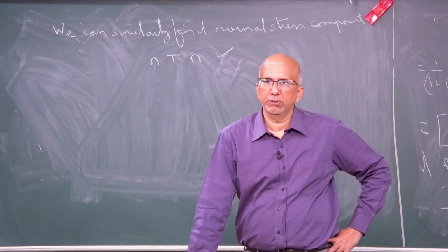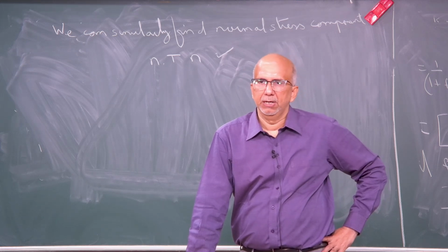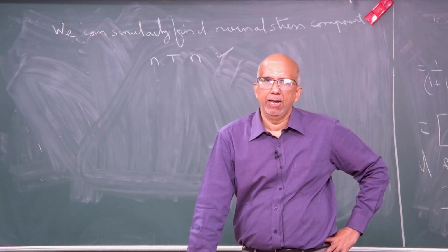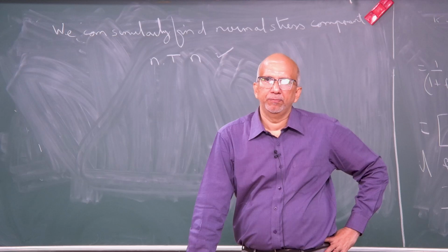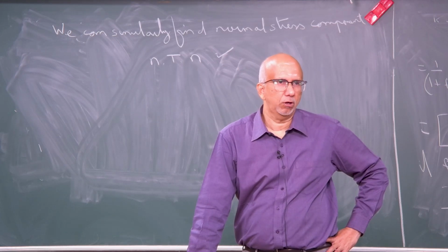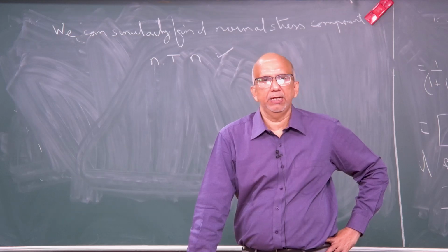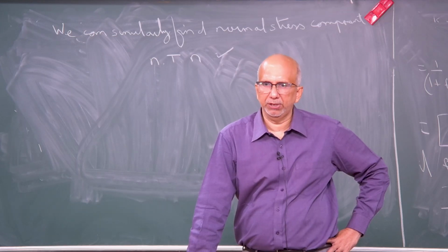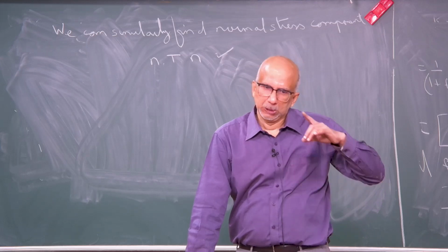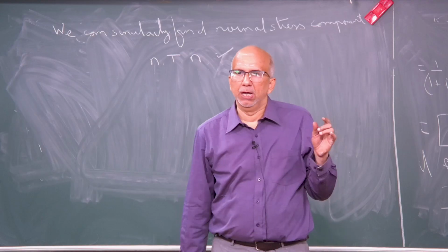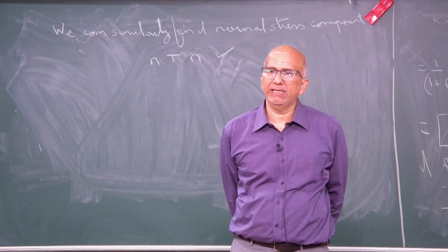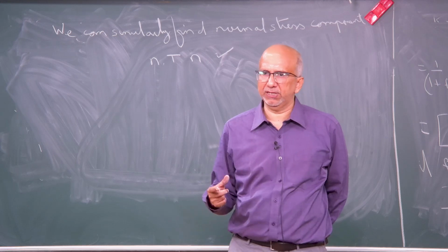So, the derivatives of the unit vectors, especially in the theta direction, are non-zero, and when you incorporate that, you get the equation of continuity and the Navier-Stokes equations in cylindrical coordinates with extra terms, as opposed to Cartesian coordinates, where you do not get extra terms.